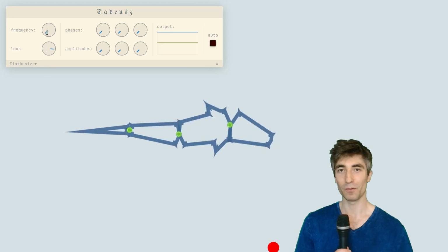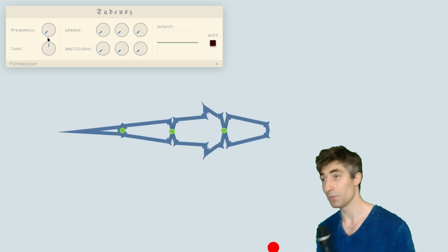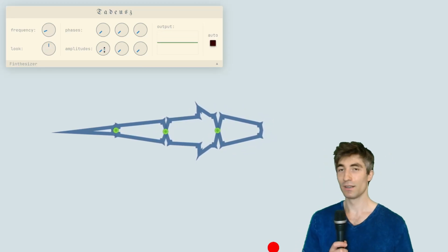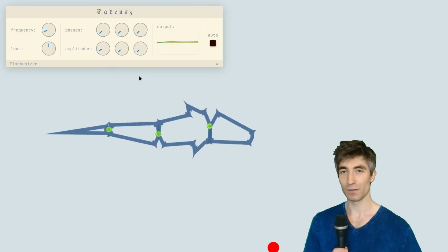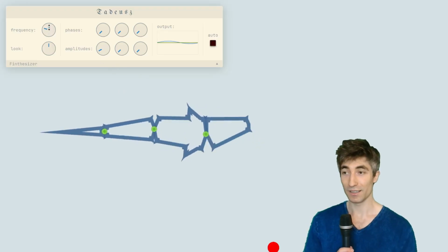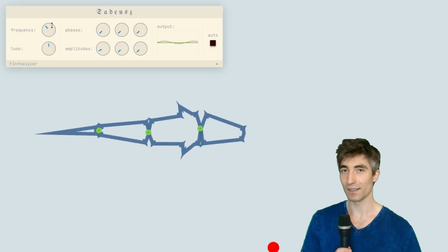The thing is, we all know how a fish swims. It moves in a sine wave. So this one is more like a synthesizer, and it has one oscillator with a dial to control the frequency, and each motor gets its own phase offset and amplitude.